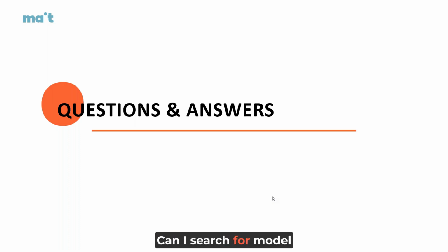Can I search for model comparisons while designing a model in a non-Creo authoring tool, specifically when the part I'm designing in the non-Creo authoring tool hasn't been published yet? Well, once more to remember, if you're working in NX, SolidWorks, Inventor, or CATIA, then you need to check in the model once. It's sent to our worker, the worker creates the footprint, and as soon as the footprint is available, you can start a similarity search with it.